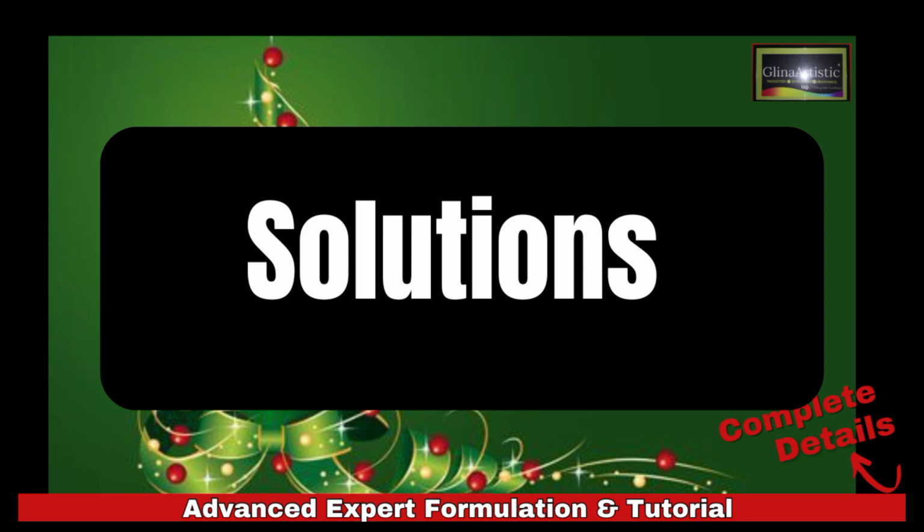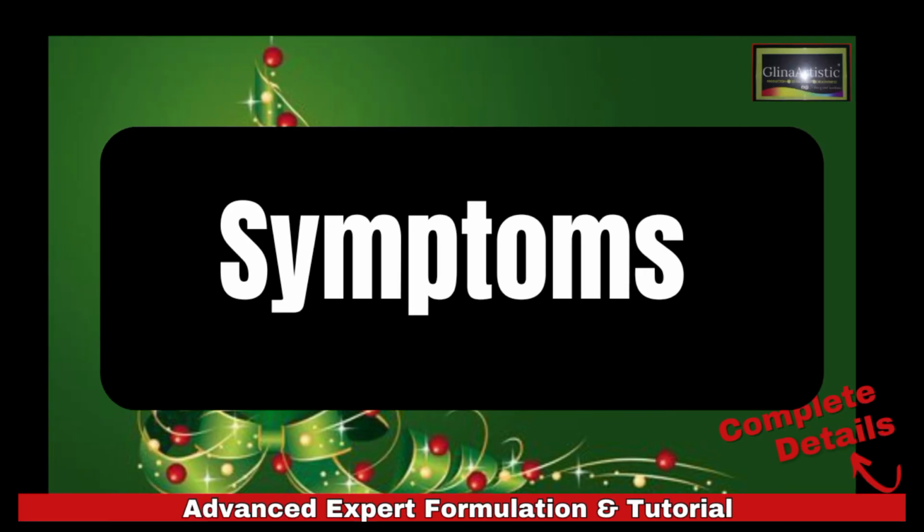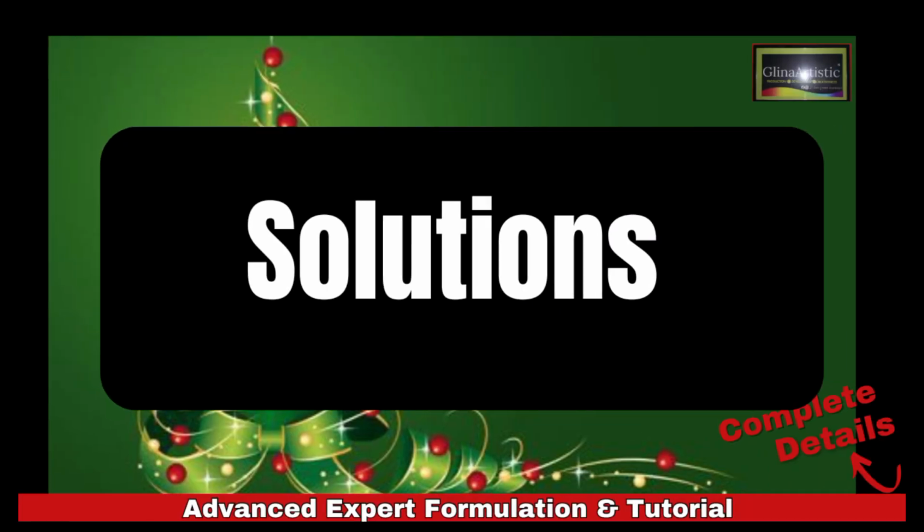So now problem number 9 is paint film defects. The symptoms are cracking, that you see the paint cracking on the wall, or pinholes, that's tiny, tiny holes in the dry paint film. Do you understand? So now, the causes are over-thinning or environmental factors. You understand? So what are the solutions? Use your plasticizers to improve flexibility and avoid excessive thinning with solvents. And you all know what your plasticizers are.